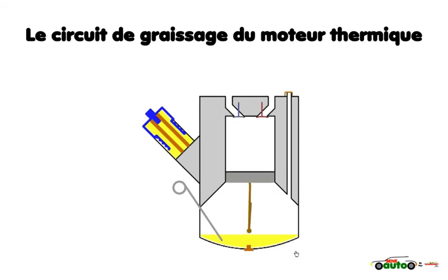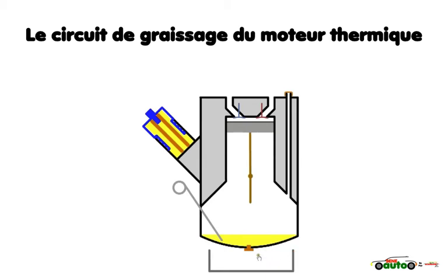Before changing oil, we run the engine for a short period to warm the oil. A container is placed under the sump, the filler cap is removed, and we open the drain plug. While the oil is draining, the oil filter is replaced.